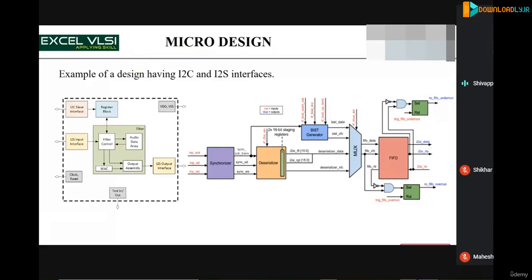So what I'm trying to say here is you will have to split up your functionality to the gate level or to the block level, the micro block level, so that it is easy for you to code in Verilog, code in any HDL. Even you can use VHDL also, but predominantly Verilog is being used mainly because of US influence. So Europe uses more of VHDL, and also legacy designs in our space you will see in VHDL. But otherwise, Verilog is mostly used by many companies today.